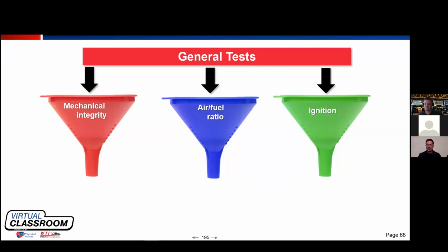And if I can get myself into one of these funnels, we call it a funnel because you start big and generalized, and every test I do is going to drive me further and further down the funnel till I'm absolutely pinpointed. And a lot of times that means committing to removing an intake manifold and removing a spark plug and going in cylinder.